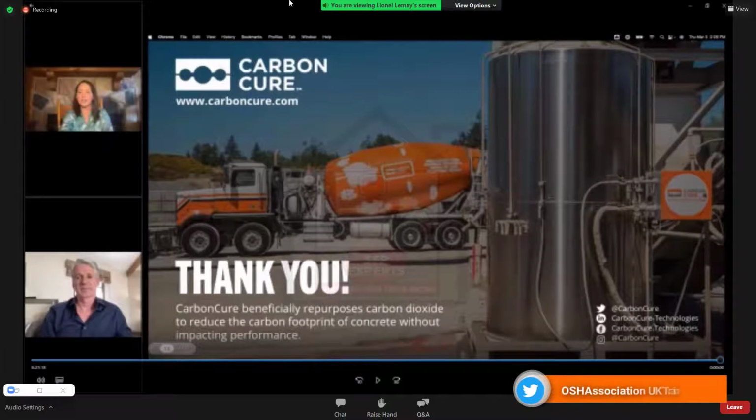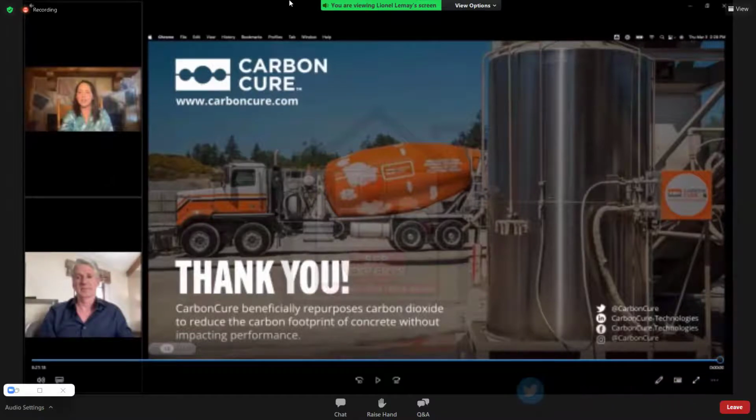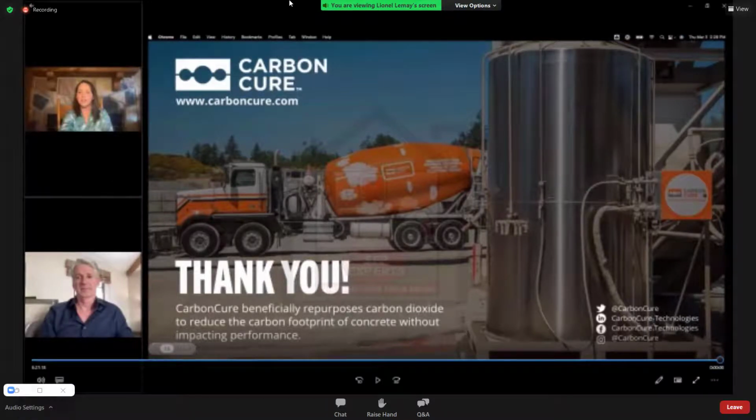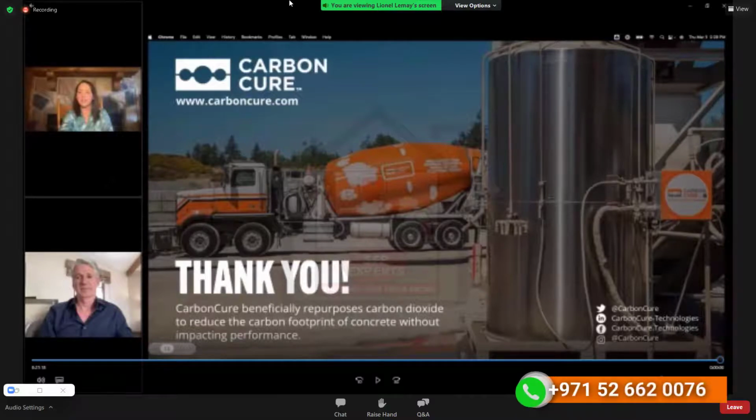But nonetheless, that CO2 is transported to a producer partner site. We do not create concrete as a company. We rather partner with producers in respective communities. That CO2 is injected in both wet and dry processes, also in precast, and I can share more information post this call. But nonetheless, when you add CO2, it improves the compressive strength of concrete without impacting the fresh or hardened properties or the performance of concrete.